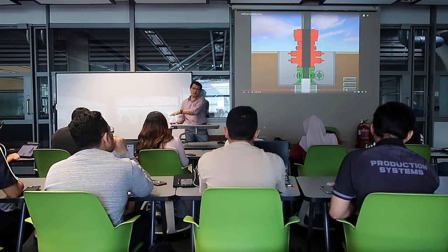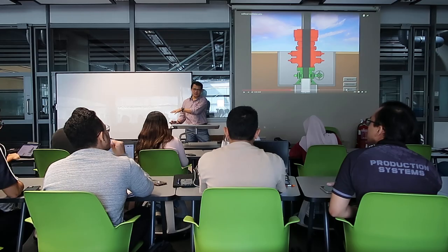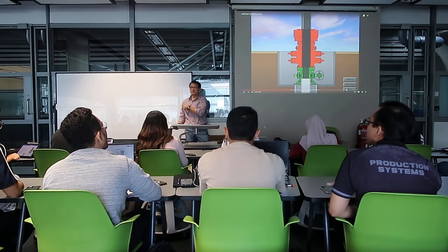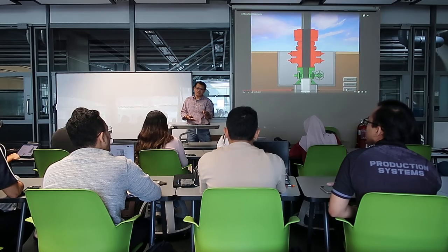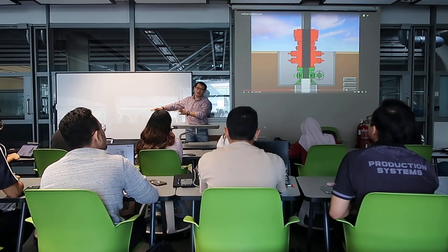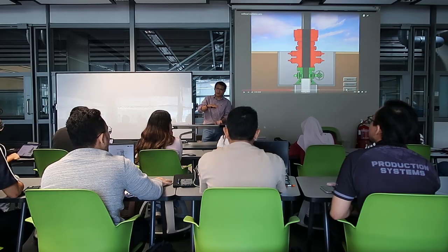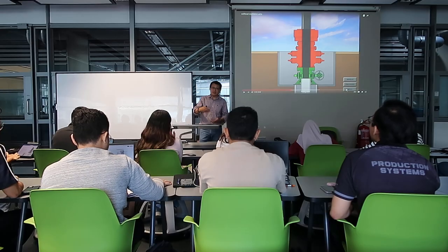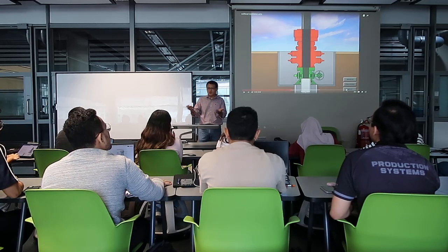They might actually do it offline, even let's say during rig cut time, but they are not using our drilling time to do the full test. Imagine if you do this offline, 8 hours is nothing. It doesn't incur any rig time. But if we put this BOP on the well itself already, we need to incur 8 hours. And that 8 hours must be waiting.